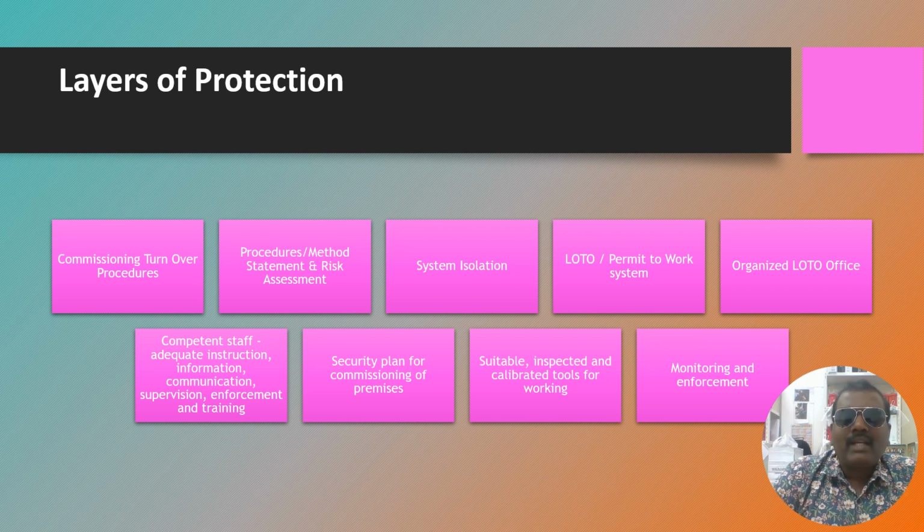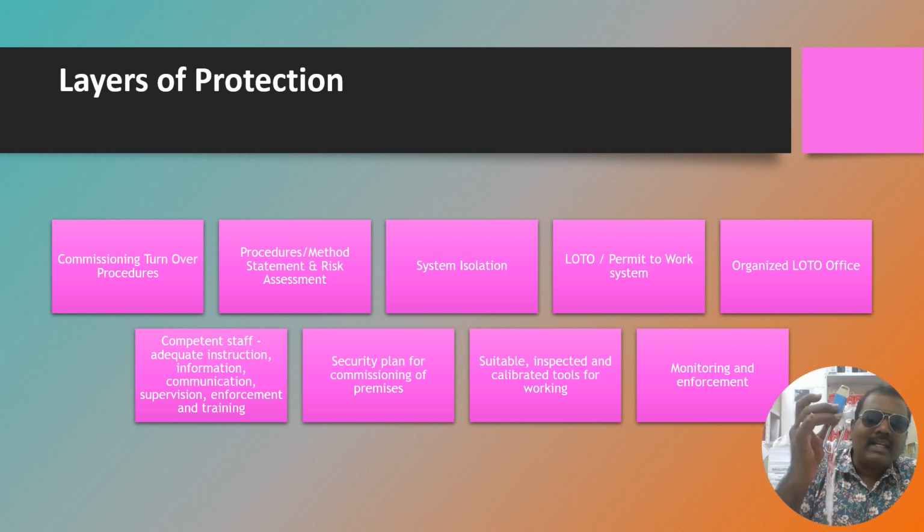Once the MCC package is approved, what can be done by the commissioning department? They can declare a notice of energization site-wide, so that each and everyone may be aware that this motor is going to be energized on this date at this time by these team members. Okay, so now we have removed this padlock and the tag from that particular breaker. Now the breaker is in service condition.